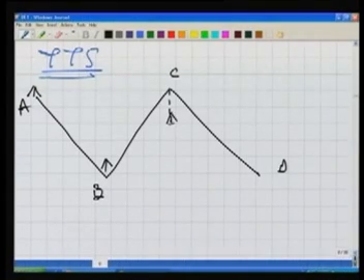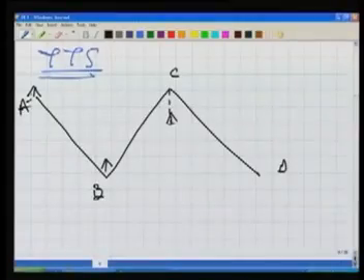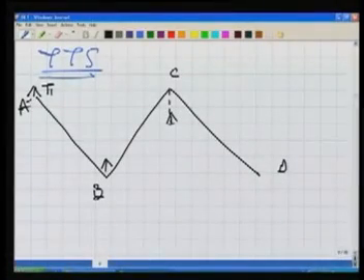So what are we doing now? We are using the same tripod, and on that tripod at some point we can put the theodolite or total station, then we take the theodolite out and replace it with the target. So our tripods are fixed here, here, here and here. Well, there is target number 1, T1, and target number 2, T2.